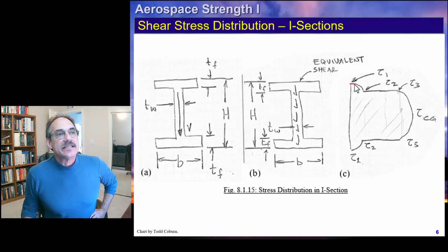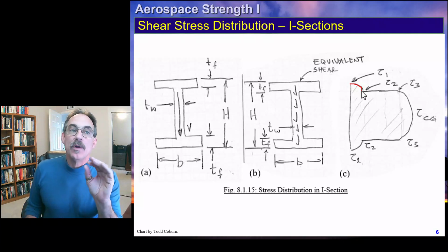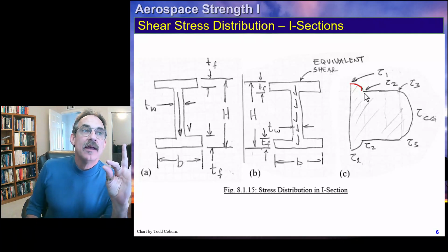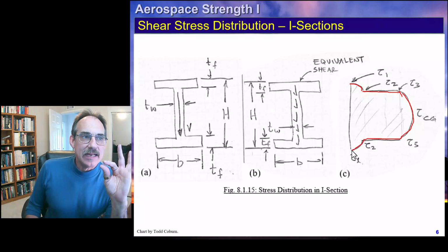Because we get that discontinuity, we're building up shear stress as a function of the V and the I with the Q that's accumulated. But suddenly that Q is divided by a much smaller number, so we get this discontinuity, and then we continue on as if we were going about the same parabola as before. Then it drops back off and back down.